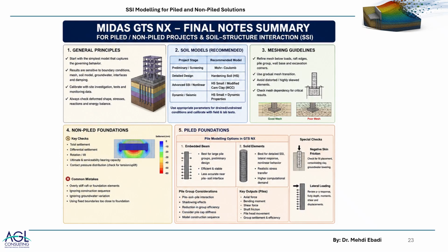For non-piled foundations, we should make sure that we are using the correct stiffness and details as per what is going to be used in the structural analysis. For piled foundations, we can either use embedded beam or solid elements. For quicker, normal, general use models, embedded beam. If you want very accurate results, it needs calibration. The calibration is different from normal calibration in MIDAS. Then you should go to solid elements.